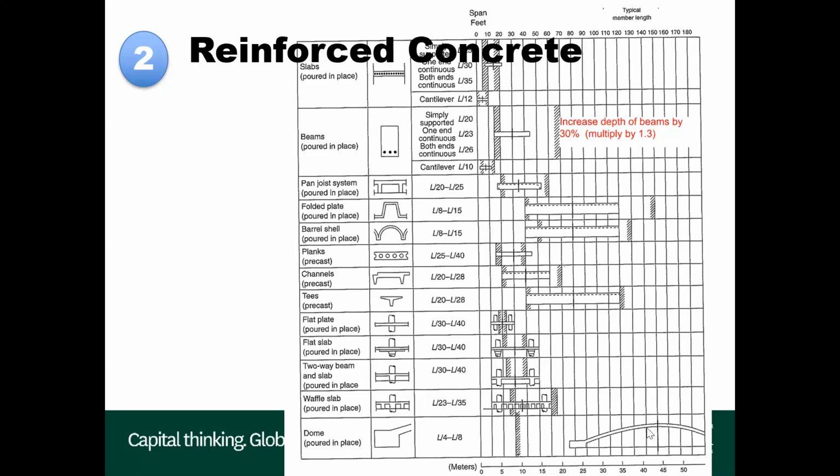And so if you've got a 50-meter dome, it's going to have a rise or structural depth of about 10 meters.